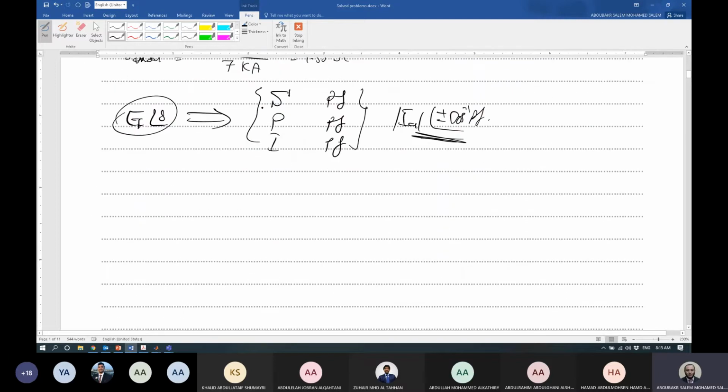So simply, we can say now IA, the armature current, equals S, which is the S of the load, over the square root of 3 times the line voltage. Of course, the machine is working as a generator here. S is given as 100 megavolt ampere, so 100 multiplied by 10 to the power 6, over V line, which is 15 kilovolts, so 15 multiplied by 10 to the power 3 multiplied by square root of 3. This is going to give you the amount of the absorbed current.